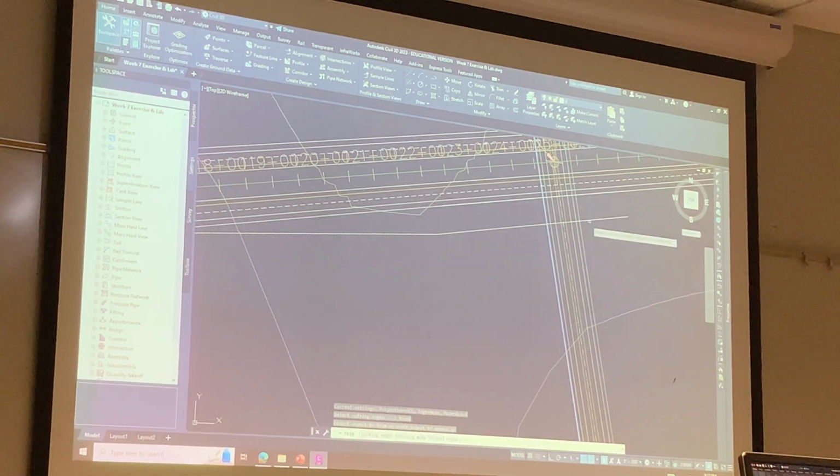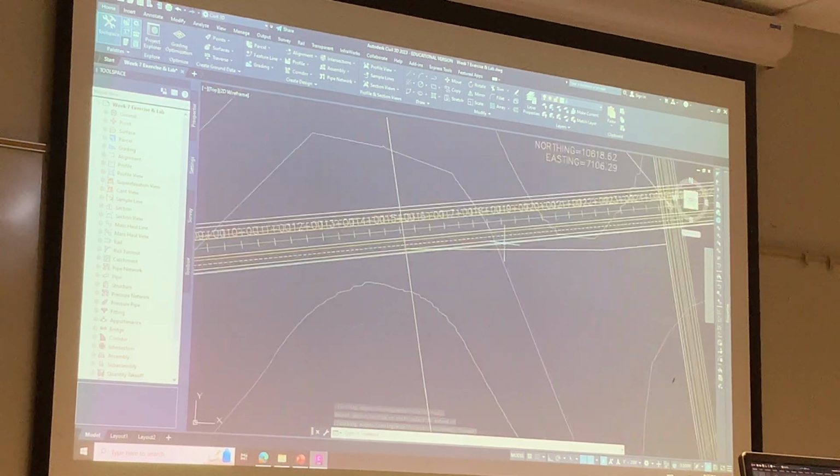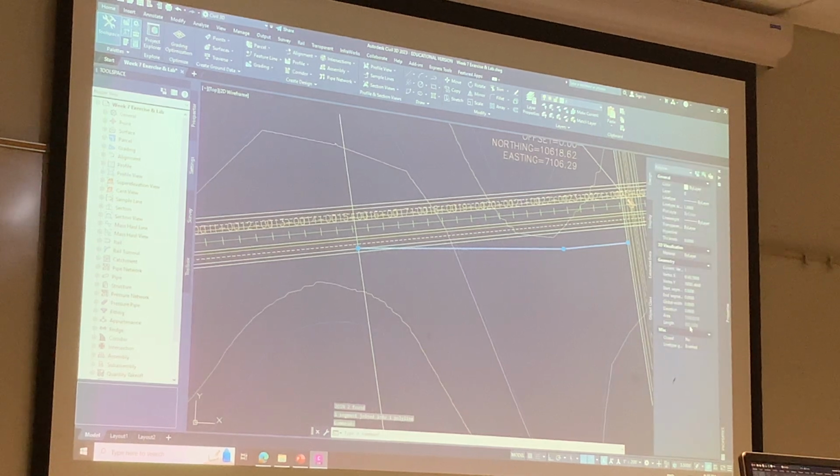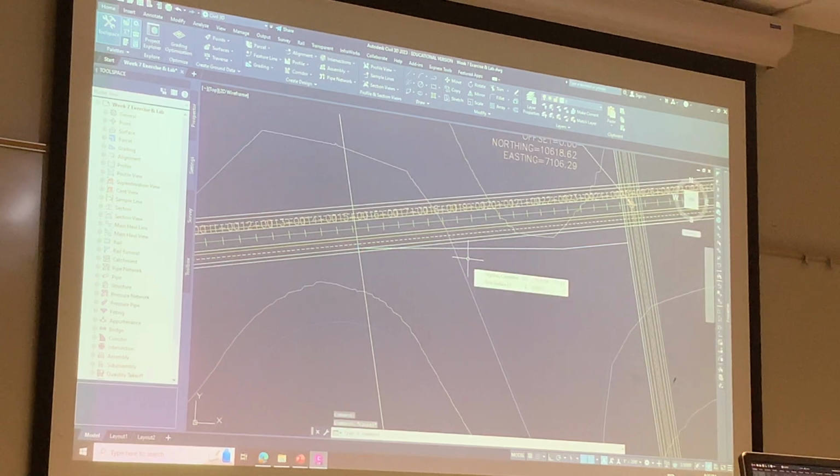I will trim this line to Catalina. So you can start to see this taking shape, right? If I were to join this right here, I can see that this has a length of 952.55 feet. This is going to be the center line of my off-ramp.